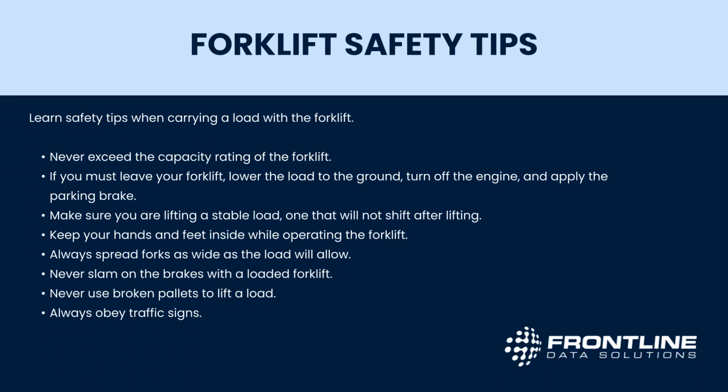When carrying a load, never exceed the forklift's rated capacity. If you need to leave the forklift, lower the load to the ground, shut off the engine, and set the parking brake. Make sure the load is stable before lifting. Keep your hands and feet inside the truck while operating. Spread the forks as wide as the load allows. Never slam on the brakes with a loaded forklift. Never use broken pallets, and always obey traffic signs.